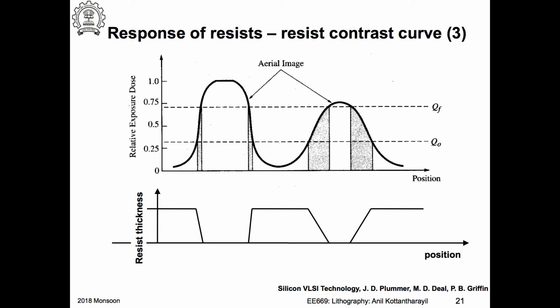Backscattering depends on the elemental mass, okay, so it gives a good contrast if you have materials of different elemental mass. For example, I can easily contrast between silicon and gold and so on and so forth in a backscattered image. Okay, so this is a very important consideration.